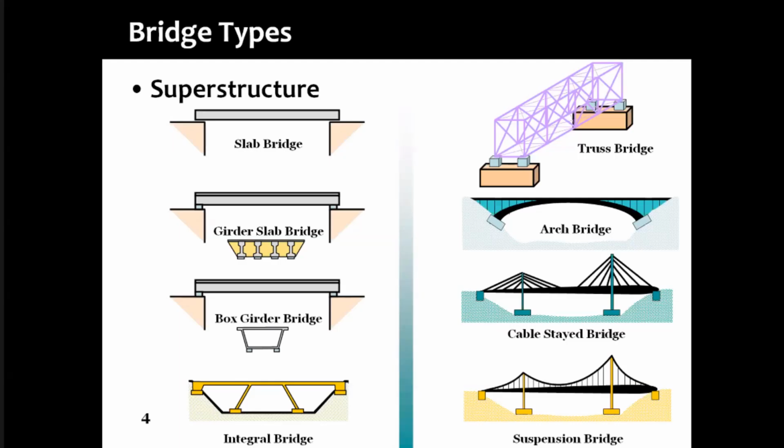And when you look at building design versus bridge design, that is the biggest difference between the two. In the building, the horizontal member must see the damage, and in a bridge, it will be the vertical member that will see damage. And that is the big difference between seismic design of bridges and seismic design of buildings. And one must have this distinction very clearly.